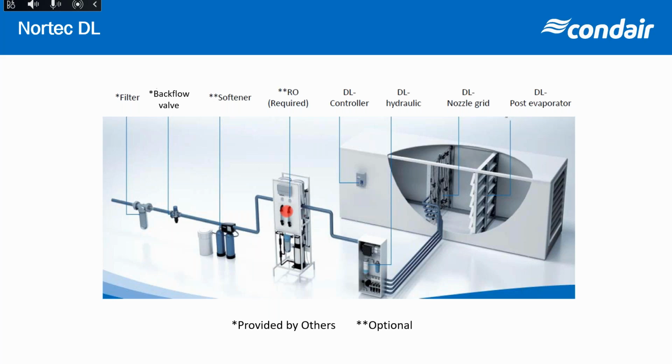And for those of you not familiar, not to be pedestrian, but what a reverse osmosis water system is that we pressurize potable water and we send it through a very tightly wound bank of filters, almost like coffee filters that are wound very tight. The good things in the water are allowed to pass through these filters. Up to about 96% of all the bad things in the water are filtered out so that our water is pure. We can go to the next step after RO, which is deionized water, where we're polishing that water to zero conductivity and zero hardness. RO water is generally defined as about 5 to 15 microsiemens and 0 grains of hardness.